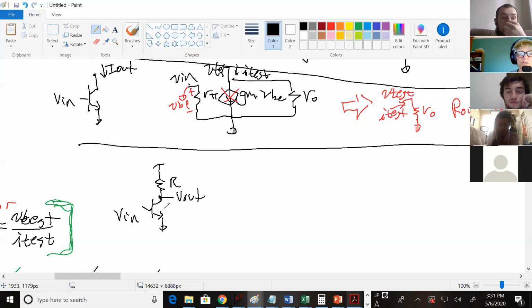So the resistor turns that current into an output voltage. And the bigger R is, the more V out moves. And how much V out moves tells you how big the gain is. So the bigger the R, the better in theory if you want a big gain. But once you get to a mega ohm, if you have 1 milliamp through your amplifier and a mega ohm resistor, that's 1,000 volts across that resistor, and you just can't build that circuit anymore.